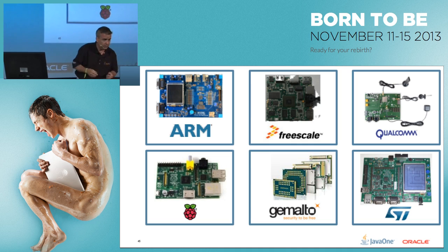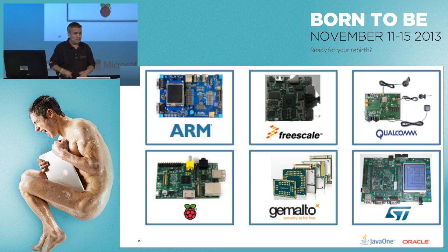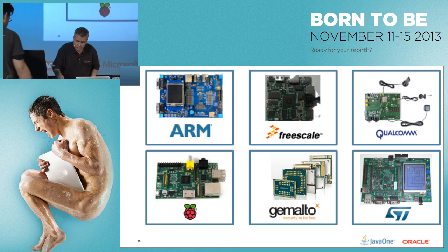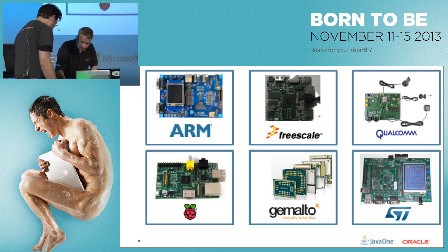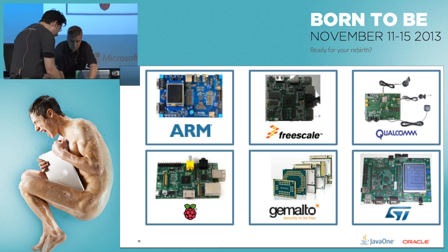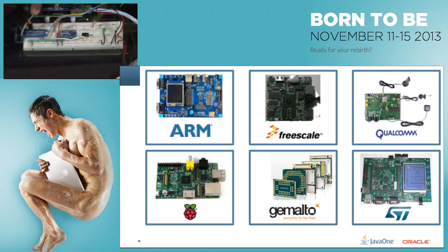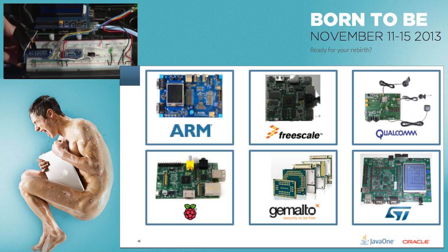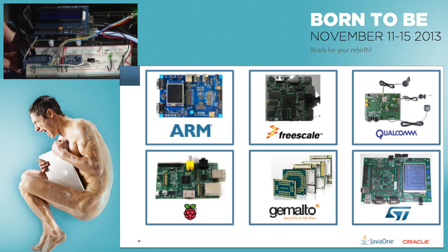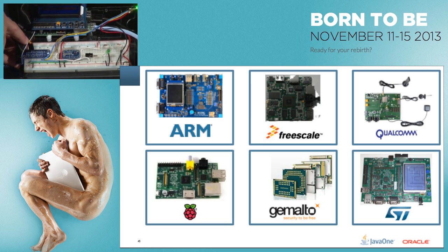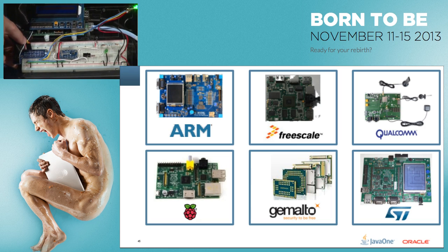So that's that board. You were mentioning serial tips, and I think I have a Pi serial tip sitting around somewhere, but it looks similar. It has connectors for the GPIO pins, but then ends in a USB end. Yeah, I actually have one right here connected to the Raspberry Pi. It's on this board right here. That connects right into my USB port on my Mac. So that's a nice way to debug the Raspberry Pi when you can't get network connectivity or figure out what's wrong with the boot process.